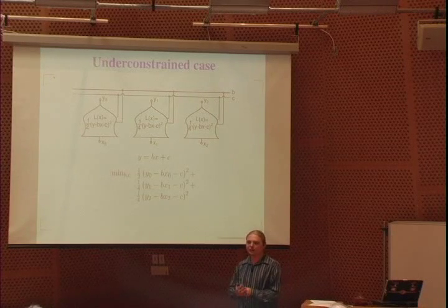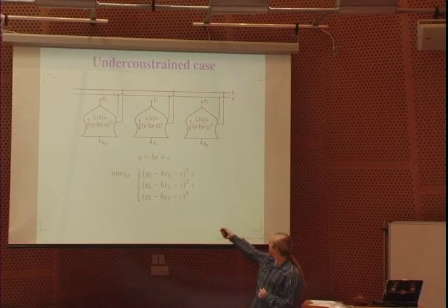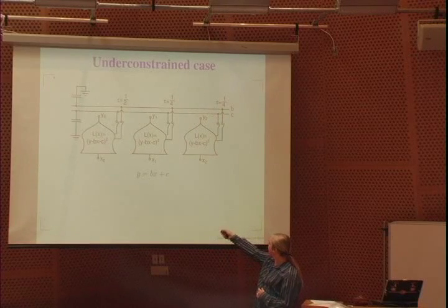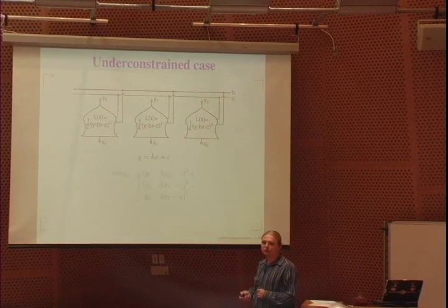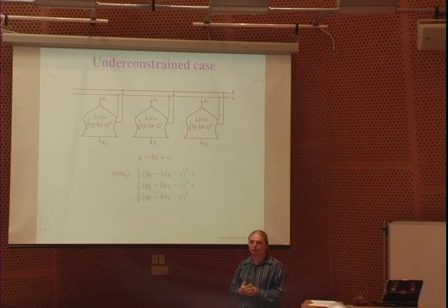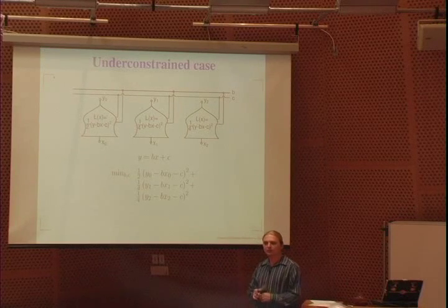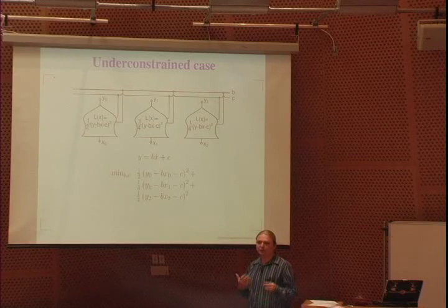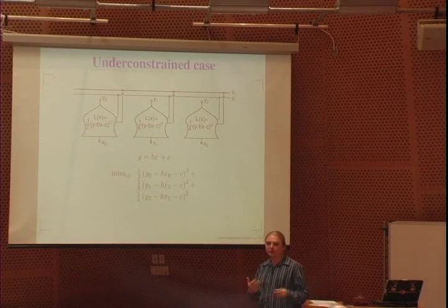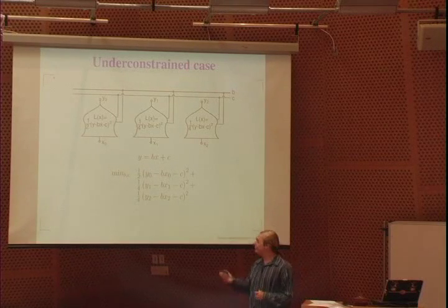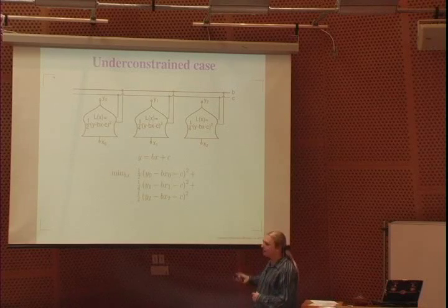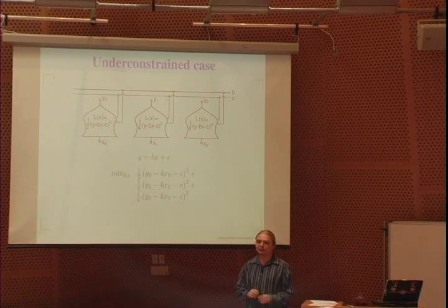And you can guarantee that it behaves that way by making the capacitances on b and c be much larger than the time constants of anything within those blocks. And that's essentially what we do. We make those capacitors really, if necessary, really big, and we make the internal dynamics of these blocks essentially instantaneous.